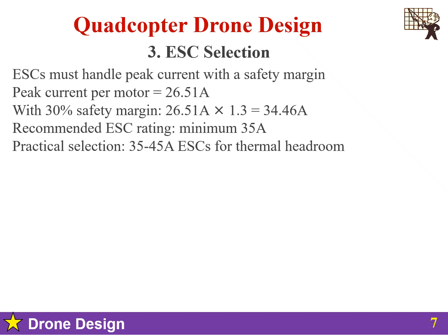Fourth, possible legal liability. The cost difference between a 35 ampere and 45 ampere ESC is perhaps $20 per unit. The cost of a single crash easily exceeds about $1,000. This is risk management through engineering design. Advanced features required. Professional grade ESCs in this range provide real-time telemetry for current, voltage, and temperature monitoring.